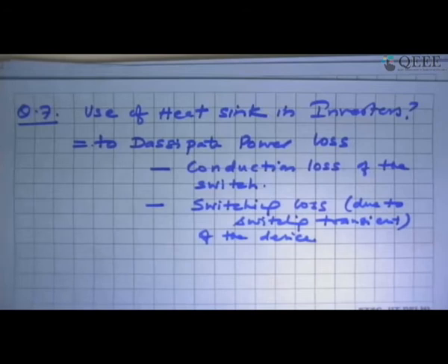And there are losses called switching losses. It depends on what kind of load you are switching on and off. You might have heard of snubbers. Snubbers are used to reduce switching loss. The turn-on and turn-off snubbers help to shape the current and voltage transients such that the switching losses come down. But if you don't have snubbers, there can be a huge switching loss.